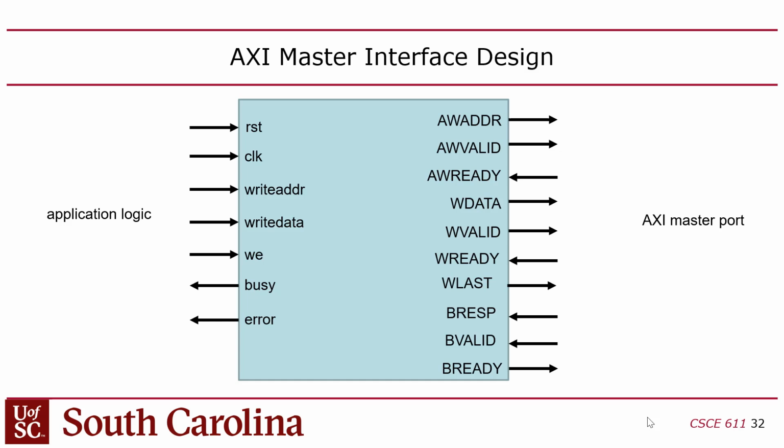And this is often called a bus adapter, bus interface, or a bridge, right? And the cool thing about this is if you can design this, then you can take pretty much anything you want and hook it into the AXI bus and have it talk to a world of other peripherals that can talk on that bus.